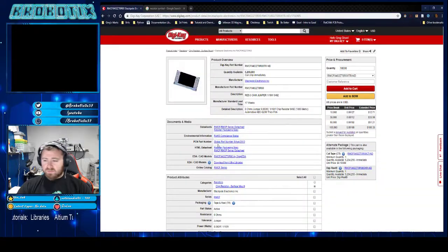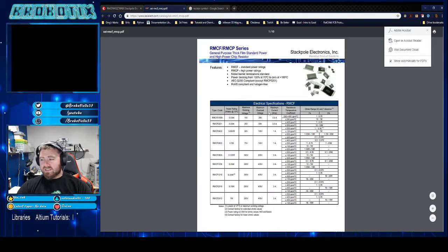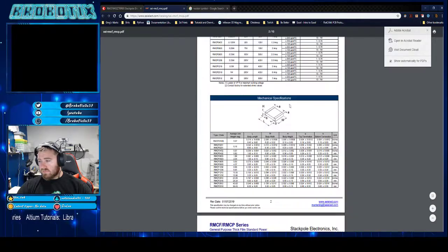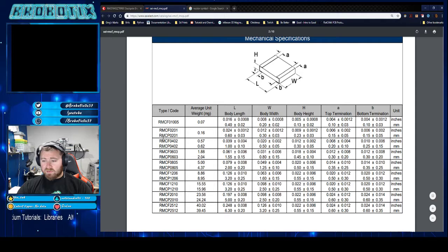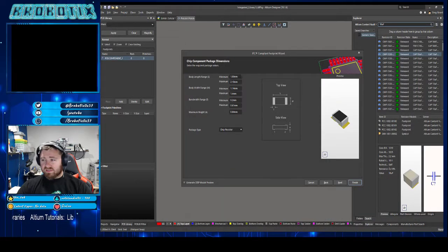If I go back to this part, series data, this spec here, I can say I'm looking at this 0402, this is an F. So I have these parameters right here. Drag this off screen so I can read it easier. Typing it in. My length, I have 0.91.